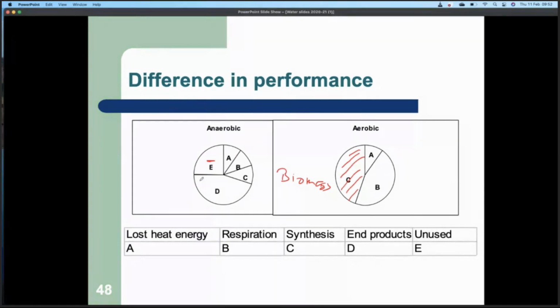And then the big advantage of anaerobic digestion, of course, is the end products. In terms of energy, this here is your methane. So you get about 40% or 45% of the energy that's in the BOD, in wastewater, converted into methane. That means the methane can be burned easily. Something previously dissolved in the liquid matrix, which doesn't burn very well, you put through anaerobic digestion, and you get about 45% of the energy contained there in the form of biogas that you can then easily use.